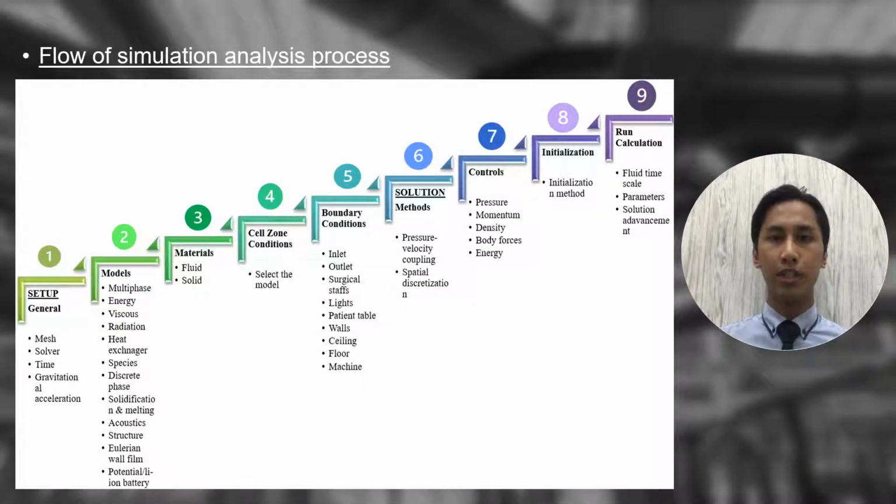The simulation is analyzed using ANSYS Fluent 2020 R2 Academic. There are three main parameters for CFD, which are setup, solution, and results. This study uses pressure-based type, absolute velocity formulation, steady time, and downwards gravity force. Tick the laminar and energy model. Next, assign air material under fluid for this solid modeling. Then, boundary conditions are assigned consistently for both designs according to the values obtained in the thermal indices. Assign the measured various air temperatures and velocities.